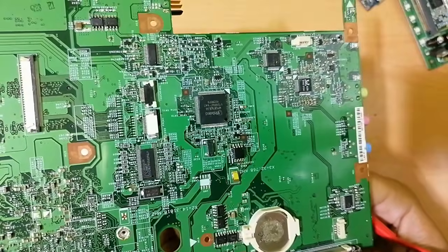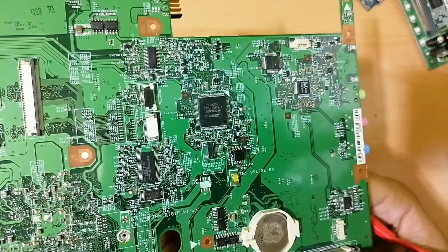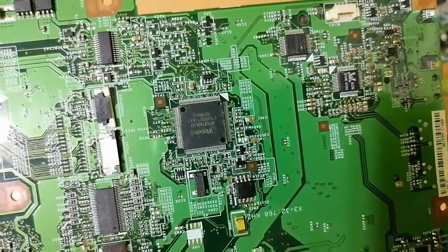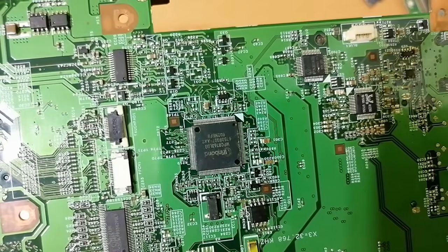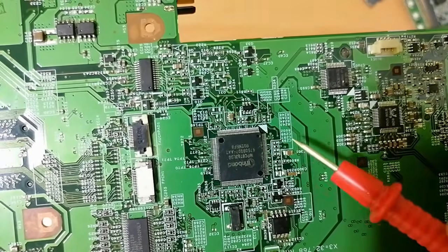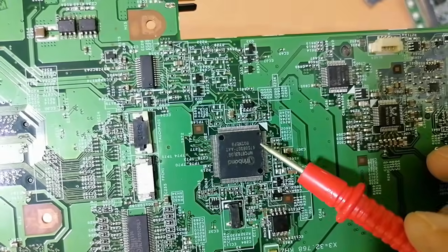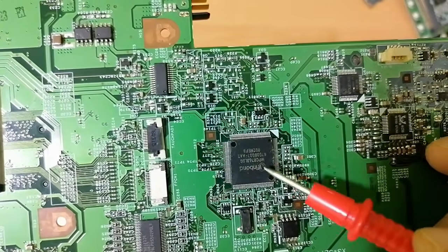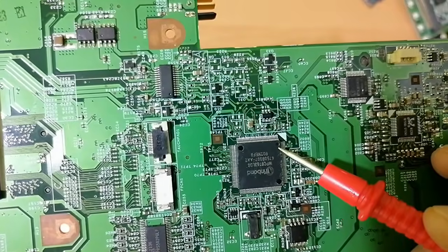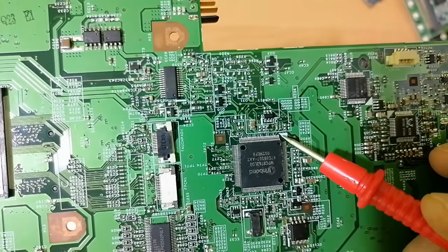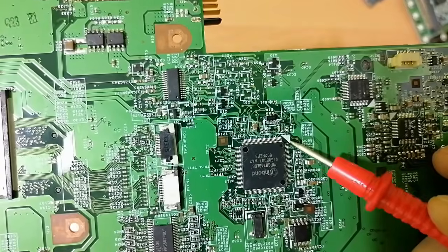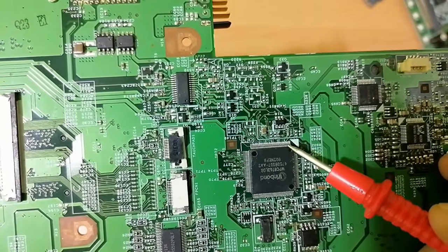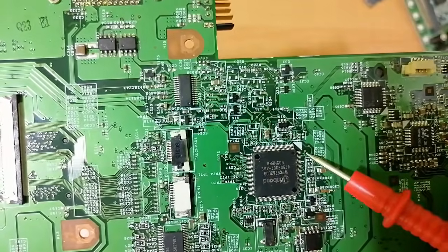First, let's discuss how to identify pin number 1 of the IC. On any IC, as you can see, you will find a hole over here. For example, for this one we have this hole over here. We have other holes here, but this is the hole, which means this is pin number 1. Or we have this triangle, as you can see here. So this is pin number 1, then pin number 2, 3, etc.